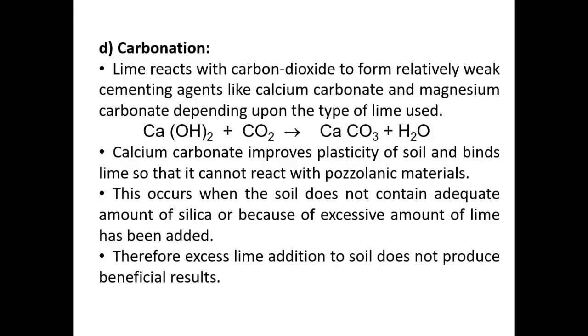The main reasons for carbonation during lime treatment are inadequate quantity of reactive silica in soil or addition of excess lime content beyond the optimum value. So to avoid the carbonation, the lime content should be estimated based on the free silica, that is reactive silica, present in the soil.